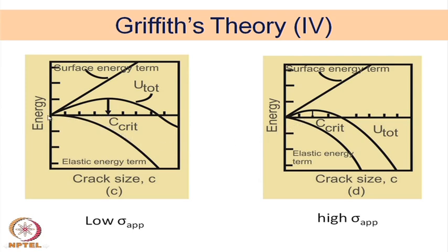So, if you double the applied stress, you will find a root 2 change in the critical crack length. So, there are many implications of this particular concept.